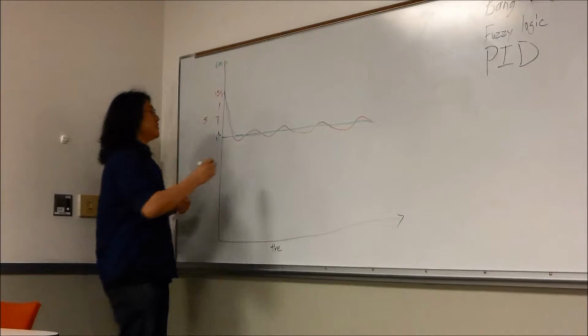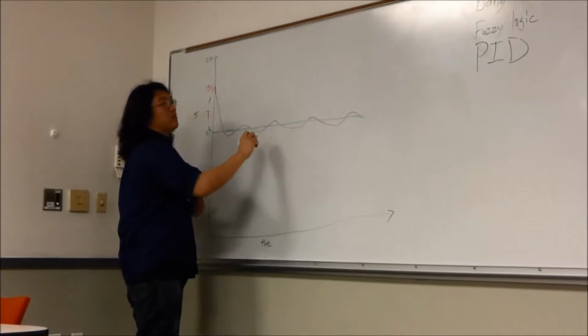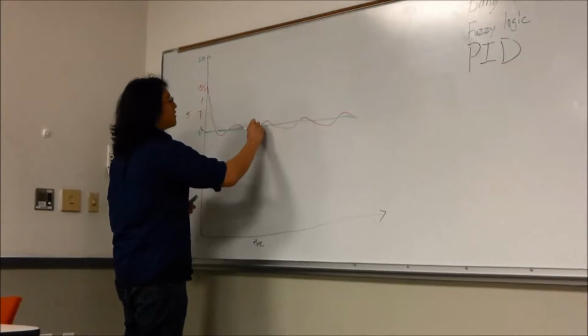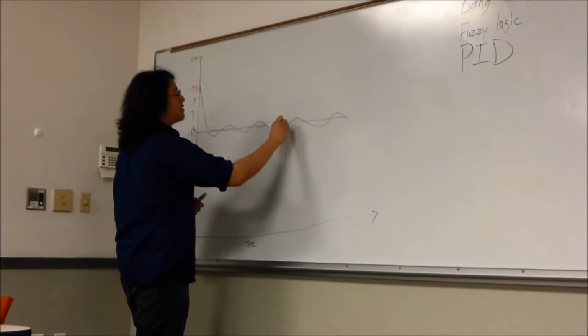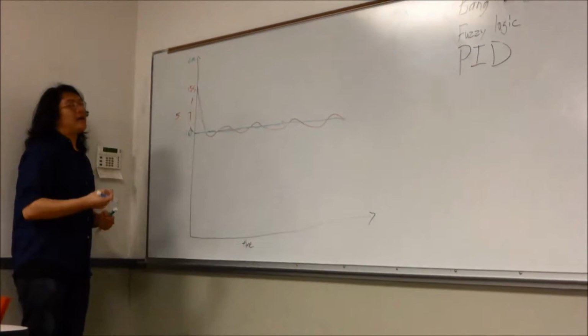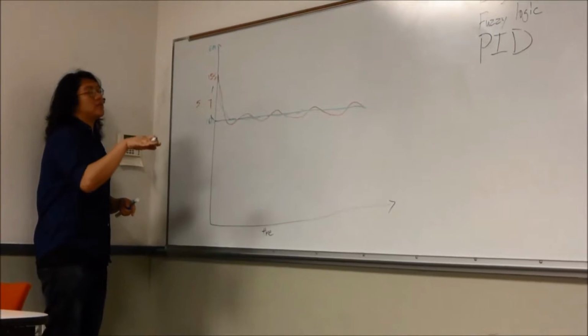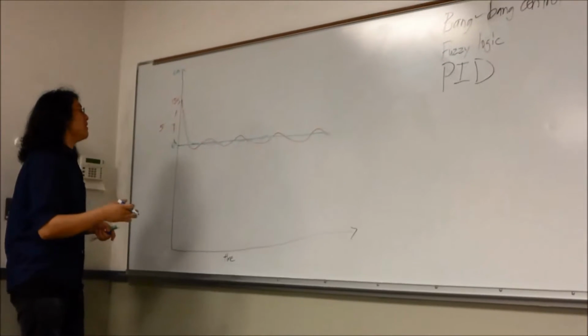The last of which is an integral term. So even with the D term, you're still going to bounce along this line a little tiny bit because of the granularity in your actuator, so you can't actually achieve this perfect system unless you add this I term, right?